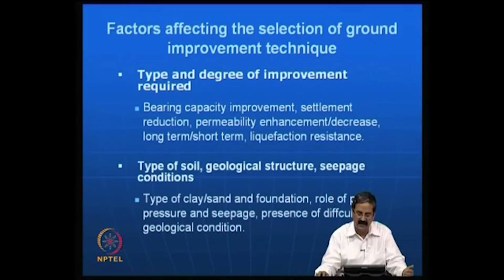Instead of going for pile foundations, one can provide only a simple raft foundation or isolated footings, so that you can place both raft foundations or isolated footings on the improved ground. The pile foundations you will be placing on the original ground, and then you have to compare with the cost of foundations when you place them on the improved ground using ground improvement techniques, and include the cost of ground improvement also.